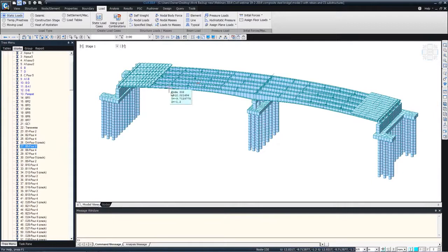The other important thing in curved bridges is that you should also create intervals whenever there is splicing to get the splice forces. So that's why you can see the nomenclature that I've used here is based on the splicing information. So if this is girder B, then I have splices at 7 locations, and I've named them separately.